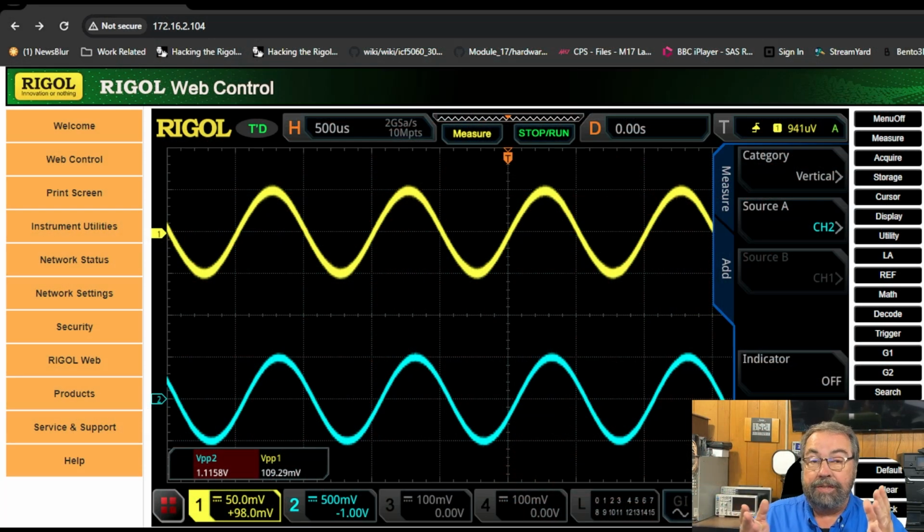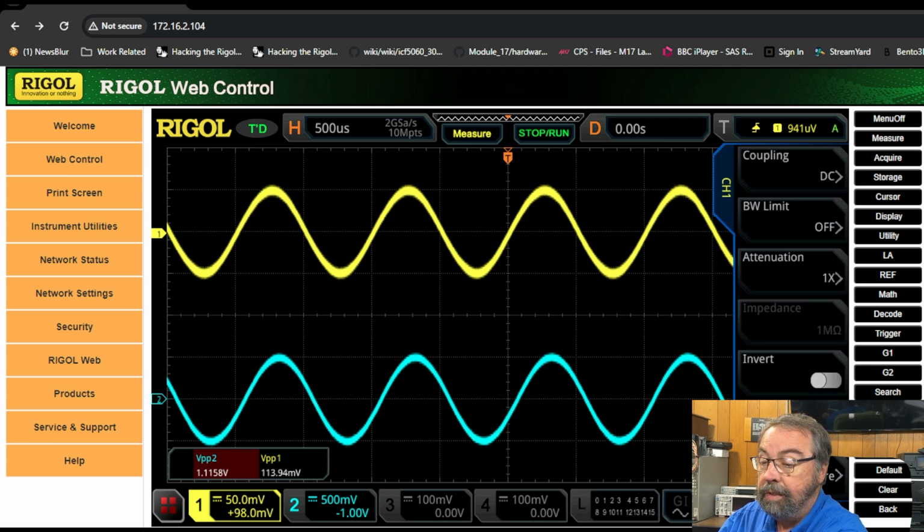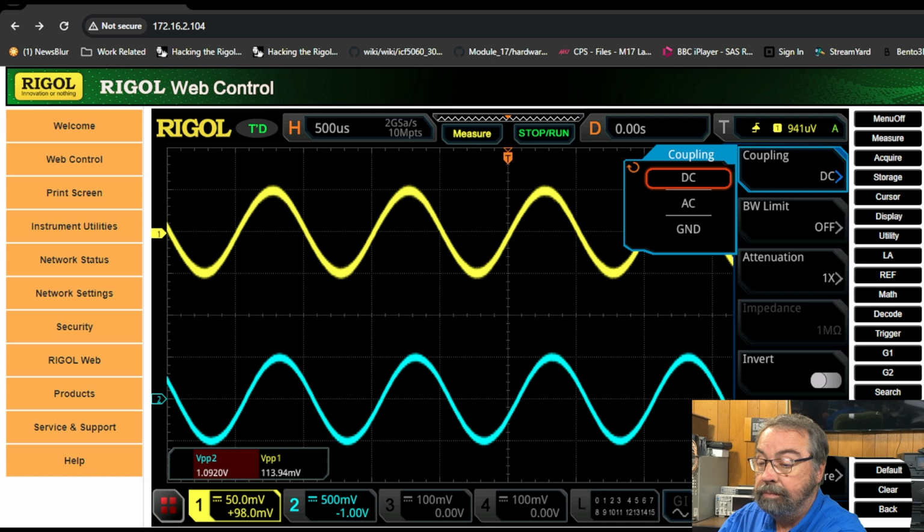Okay, so I've got this scope set up, and this is the Rigol 5074. This is the same exact scope that Smoking Ape has. I want to show you guys the settings on the scope side. I've showed you the uni-t Sig generator settings. So on this guy, we have channel 1 on, and channel 1 is going to be AC coupled.